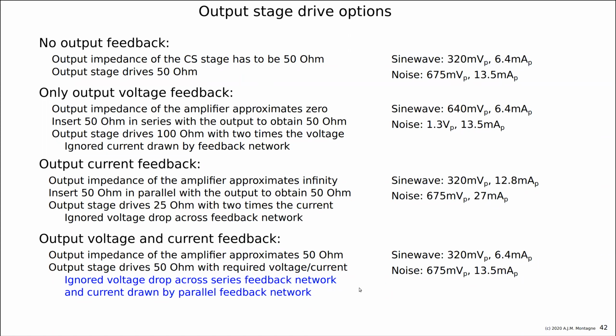But the big picture is here. And unfortunately, no one has been looking at this picture in the exercises, but this is something that has to do with the architecture of the complete amplifier. How are we going to drive this 50 ohm? Do we do it with feedback, with dual loop feedback, with single loop feedback, or are we trying to design the output stage, the transistor, having 50 ohm output impedance?